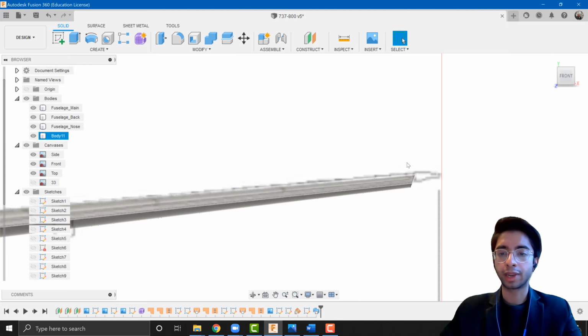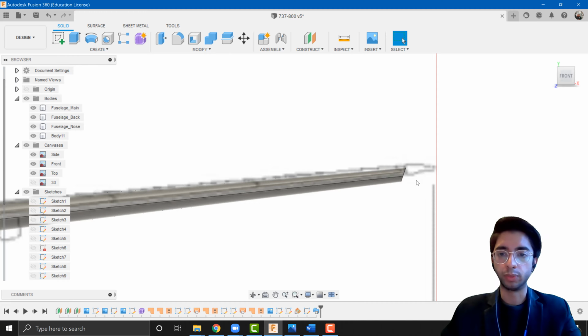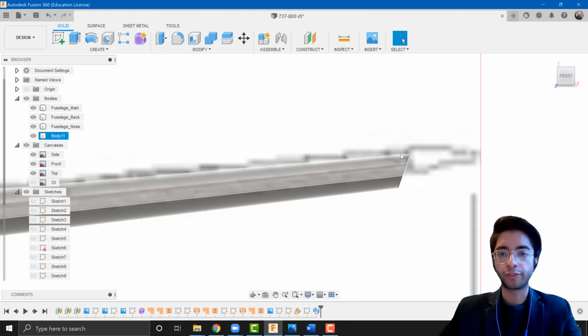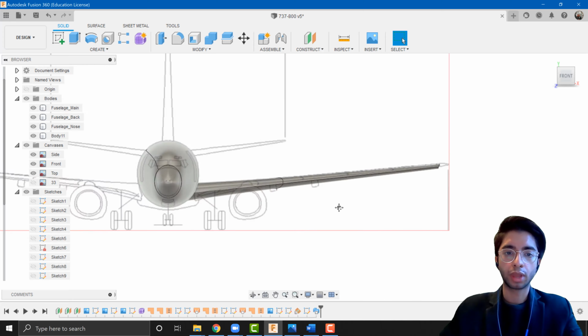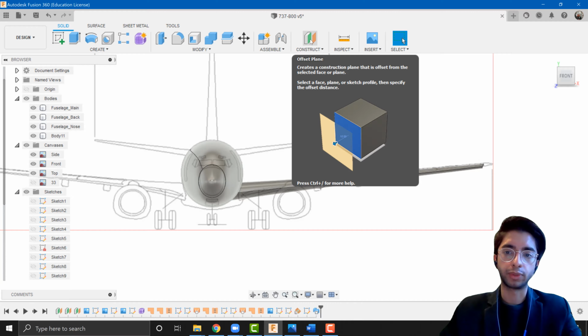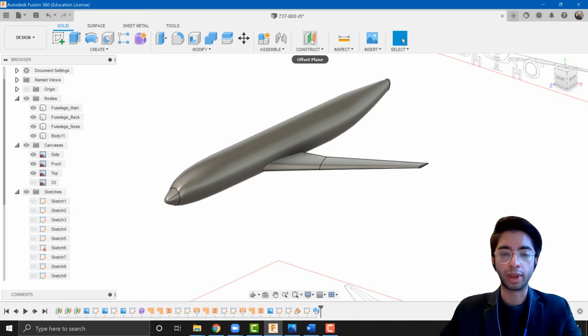Okay, so now what we want to take care of are the wingtips. So the one that I've chosen here doesn't really have any weird wingtips or anything fancy. It's pretty straightforward, just an extension. And the way we have to deal with this is we're first going to chop this wing such that the end of it is vertical. Now the way to do that is I just construct a plane and I use that plane as a knife to then cut the wing. I'm sure there are other ways of doing this, but this is the way I use it.